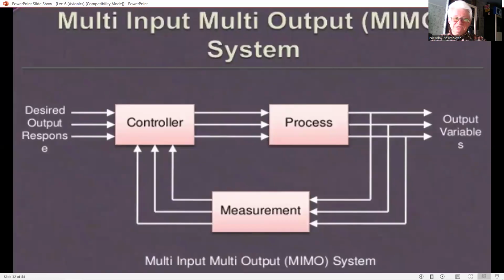Flight control systems come into the category of multi-input multi-output (MIMO) closed-loop control systems, as control is exerted about three axes and there are six degrees of freedom. The classical control theory approach is very suitable for single-input single-output (SISO) closed-loop control systems, and some single-input multiple-output (SIMO) systems like two outputs.